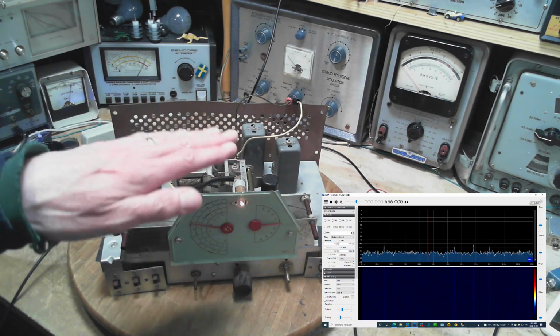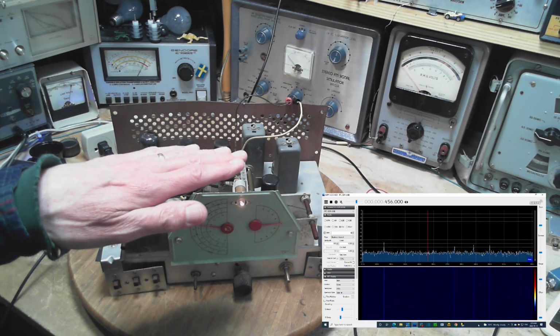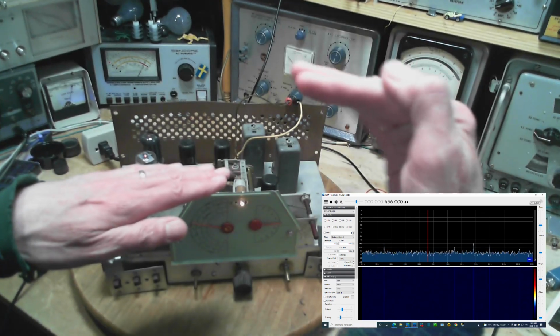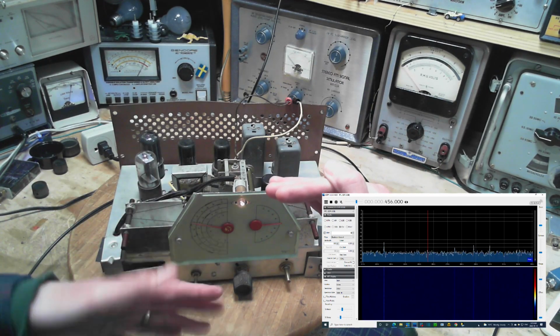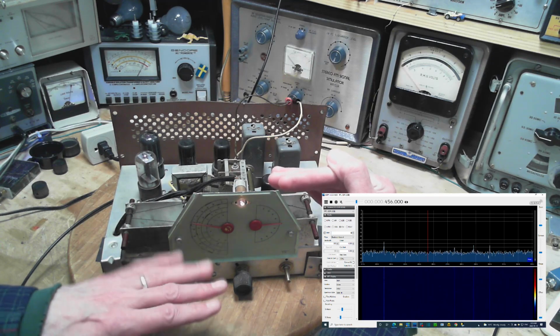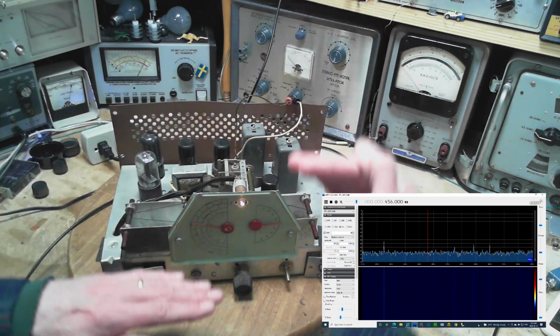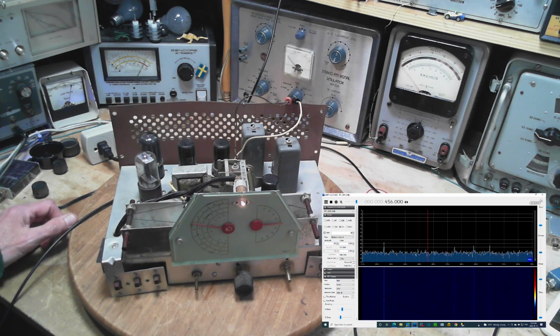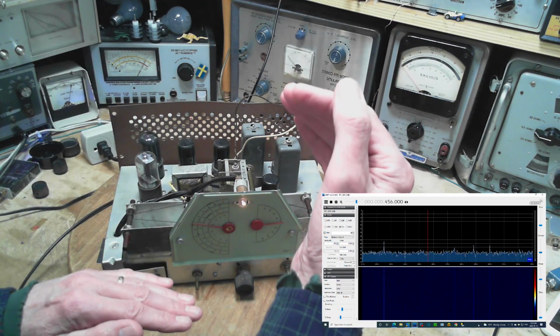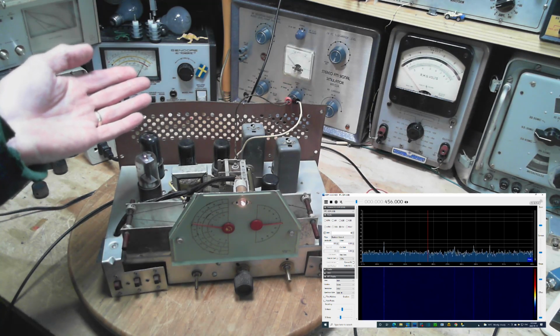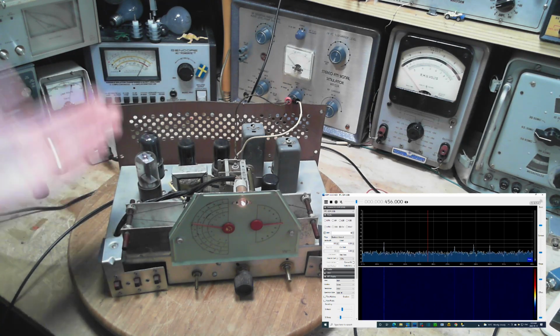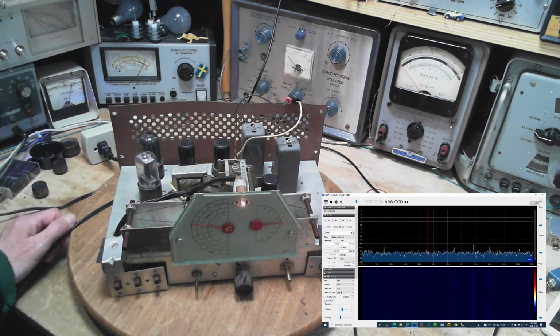So first we have the noise we're listening to on the IF, which I'm curious about. Then we bring in another noise at a much higher level, and the radio turns everything down. So this sounds a lot quieter, maybe too quiet to hear. It's still there. It's just we're being fooled by the AVC voltage. If it's brought down to the point where it's too quiet to hear, who would care about it? Maybe that's one of the goals of these radios, or one of the factors, that the noise coming in at the IF frequency is so low as to be ignored.